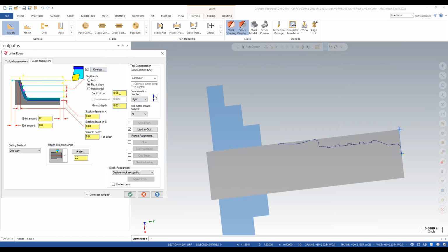So back to this. 50 thou depth of cut. If you go anything more than 50 thou depth of cut, everybody look at me, you're going to stall the lathe. We're going to get really close to stalling it on purpose just to show you how to max the thing out. Sound good? Don't go more than that depth of cut. Cool. I'm going to push it on my demo to show you the wind down and wind up. It'll be cool. So at this point, we have a slight.